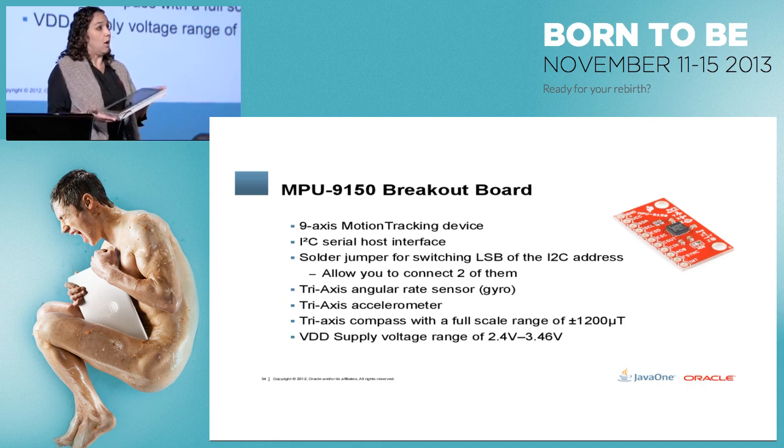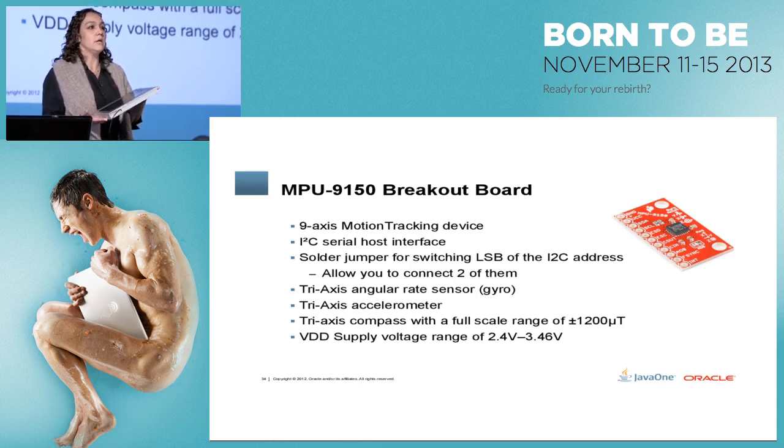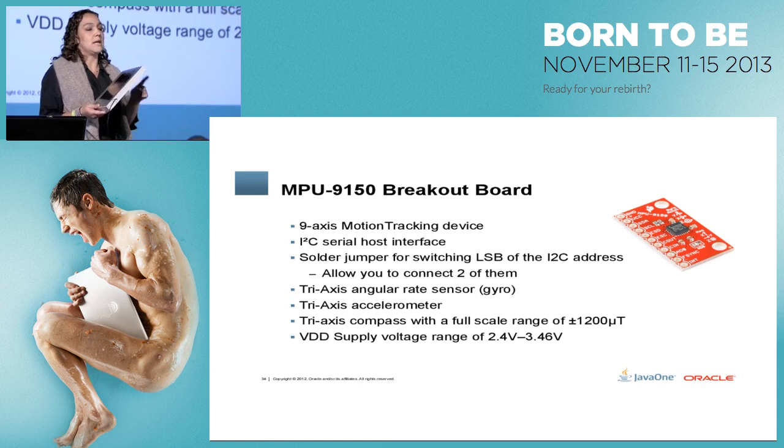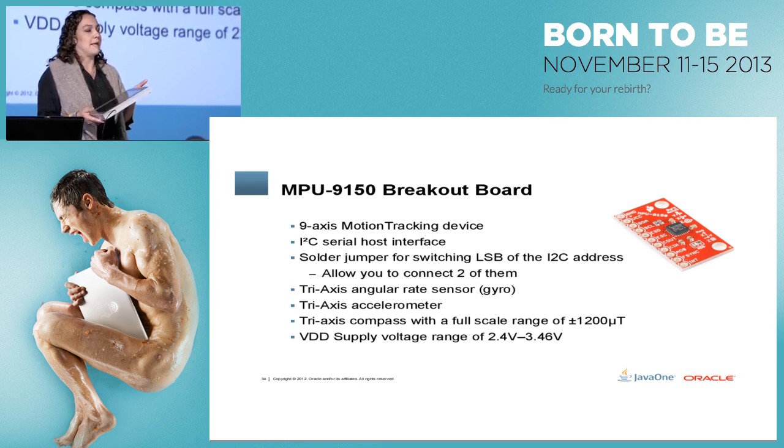But as I stop, the acceleration is 0. So the gyroscope is not going to give me any reading once I stop, even though I do have some inclination. This is when the accelerometer comes into the picture, because the accelerometer can tell me what the angle is, because it measures the angle against gravity. So I really needed both.